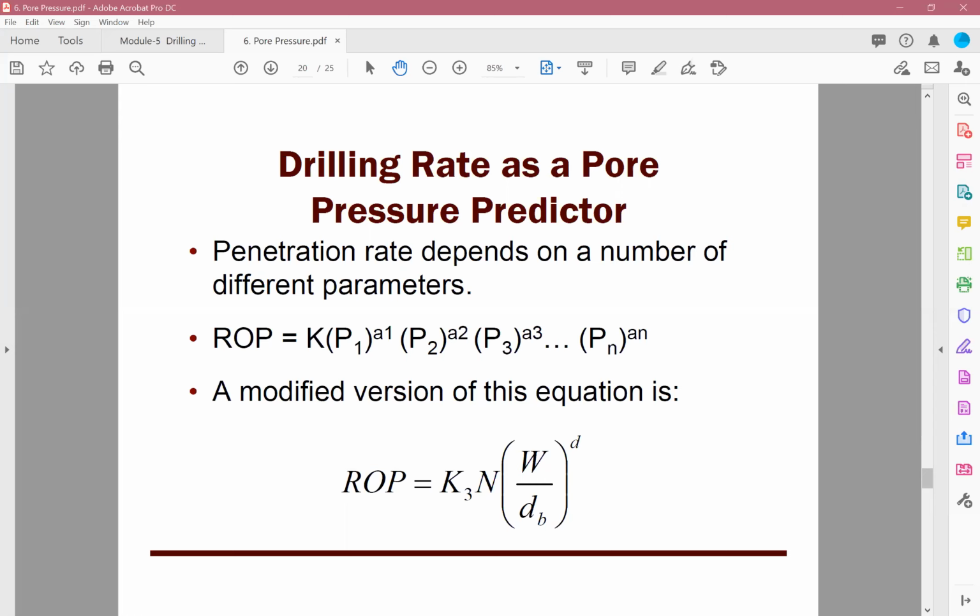So lower mud density is one factor. Matrix density: if you have harder rock compared to soft rock, that would definitely change your penetration rate. What else? The type of bit you use. The type of bit, definitely. There are three main drill bits, and each bit is designed for a specific type of formation. You did some calculations when we did the drilling cost per foot calculations. Different drill bits may have different rates of penetration. What else?